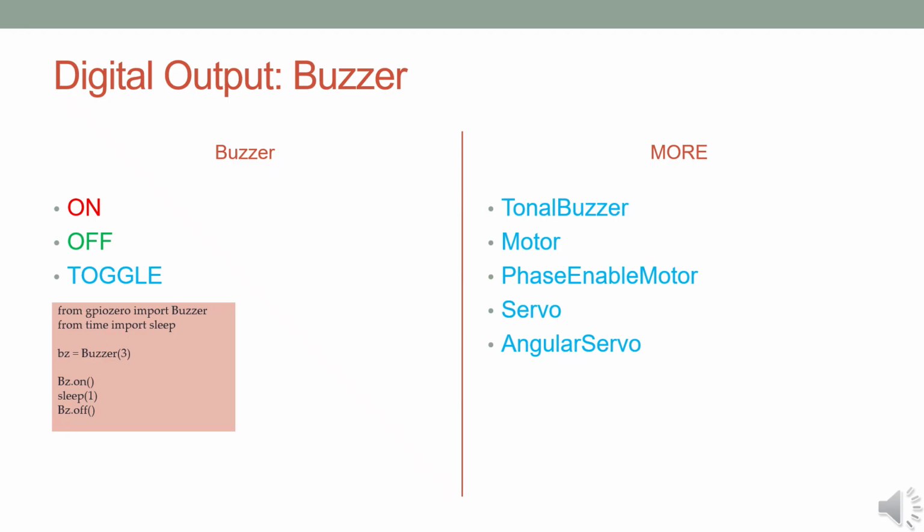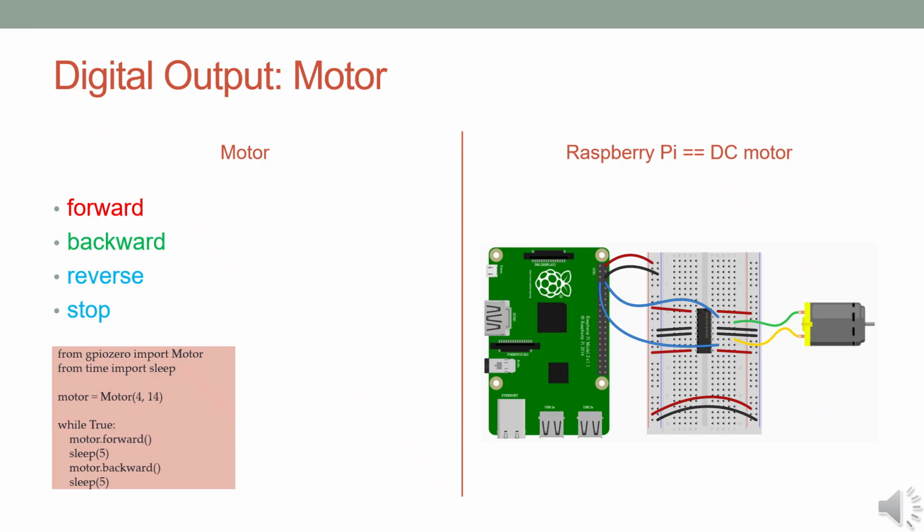Once the object is defined, you can control the device as a whole, making the programming process much easier and more intuitive. This image provides another example, this time demonstrating how to control a motor using gpiozero. In the sample code, we rotate the motor forward, stop, rotate it in reverse, stop again, and repeat. This is done easily using composite commands in Python.